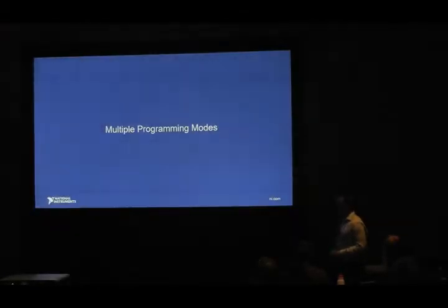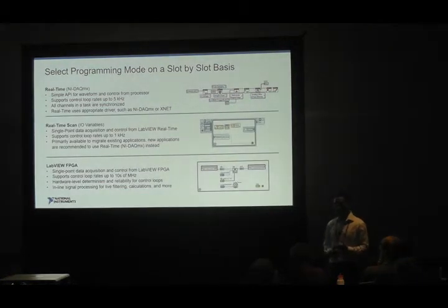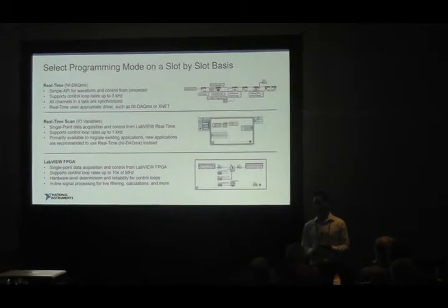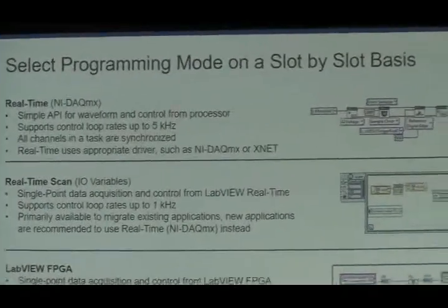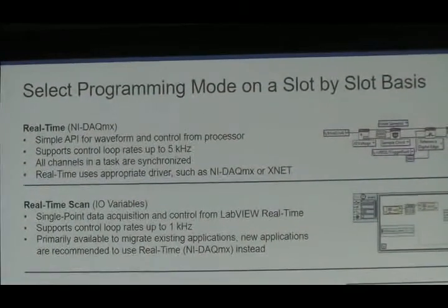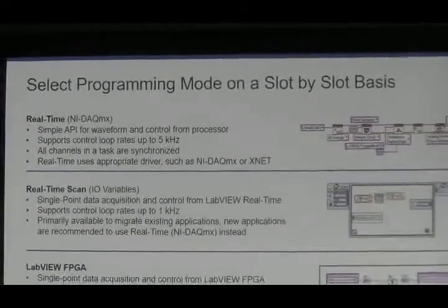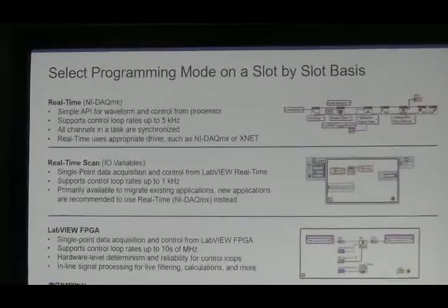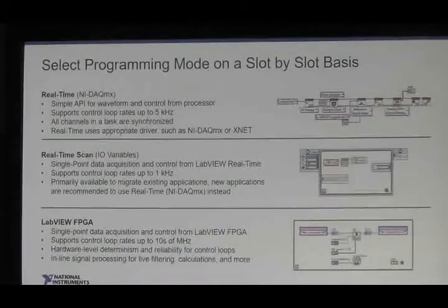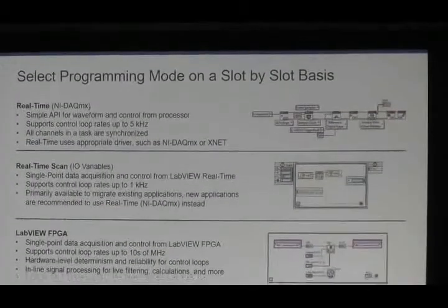Going into the multiple programming modes, there are three programming modes that are supported on a slot-by-slot basis for these new controllers. One is called real-time, the next one is real-time scan, and the last one is LabVIEW FPGA. Real-time is going to cover drivers like DAQmx or XNet, so obviously DAQmx for its waveform streaming capability, and then some of the other processor-based drivers such as XNet will all be supported within this programming mode.